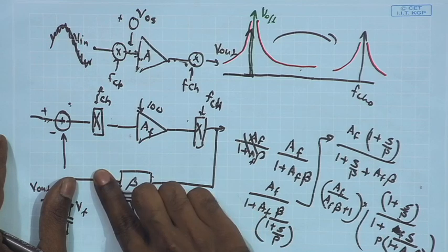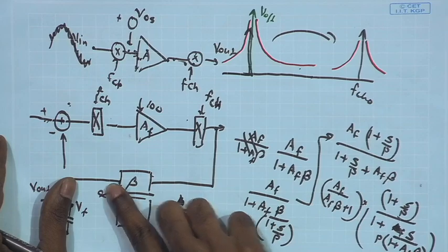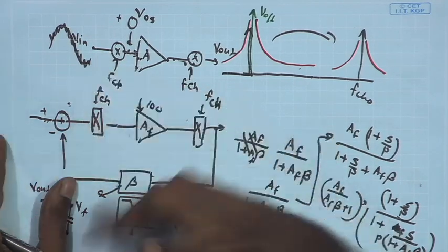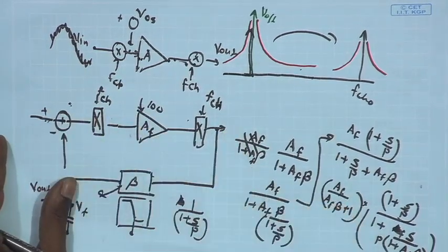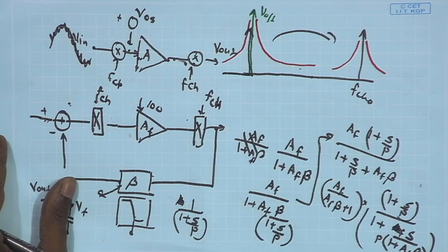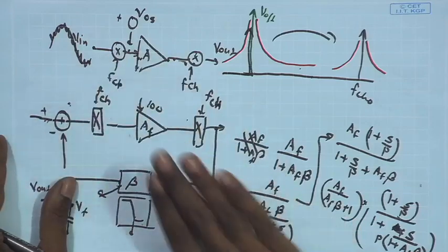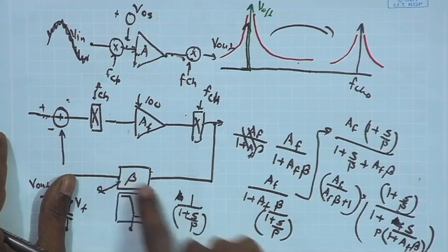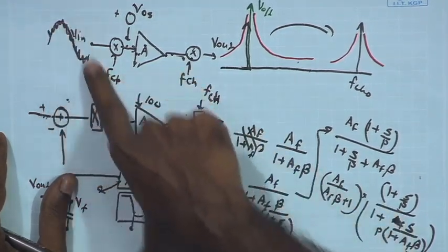So, if the beta here is greater than 1, that means from here to here you are trying to put gain, and the moment you put some active circuit to put a gain, that means again noise contribution is going to come. That is required to keep beta higher and then suppress the undesired signal, but at the same time it should not corrupt the signal with additional noise in the circuitry. So, this loop becomes very critical, and we need to see how to come up with an appropriate design catering to the beta requirement, the noise criteria, and cancellation of this wide swing dynamic signal.